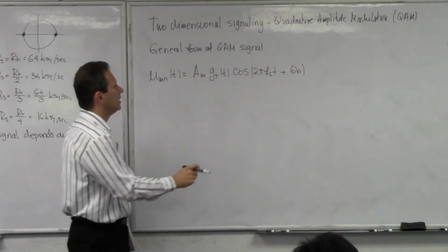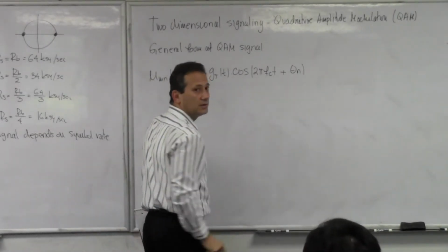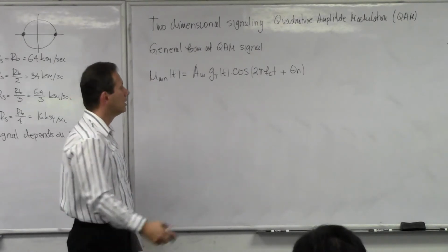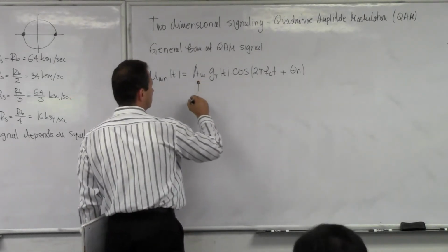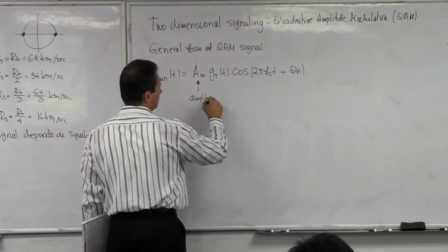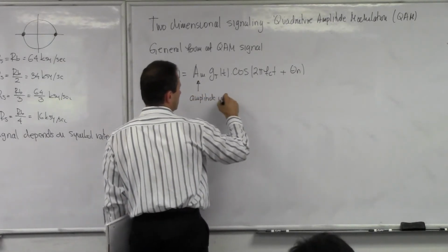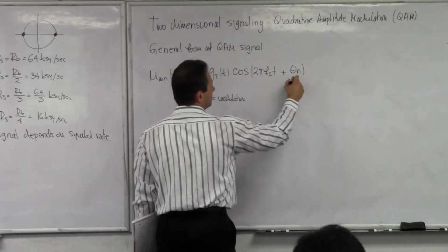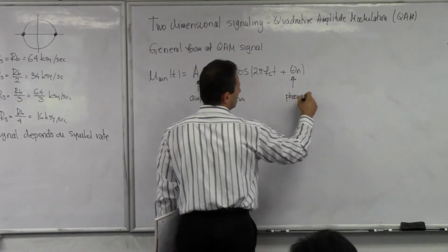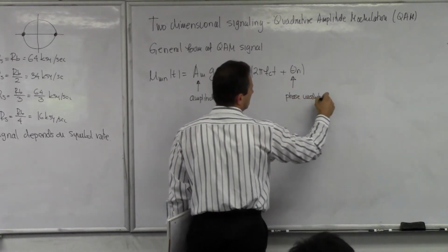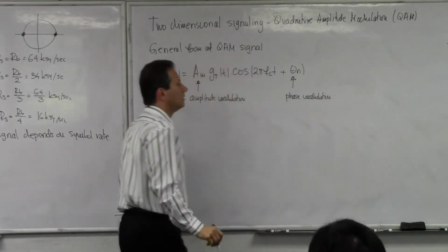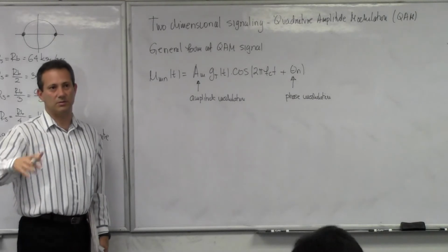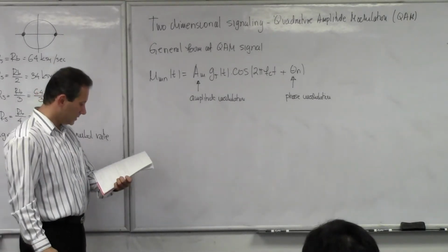In the case of the PSK, we messed only with this theta here. We had different angles, you know, as a function of whatever comes in. Here we have amplitude modulation and phase modulation working in, you know, in parallel. So we change the magnitude of the symbol as the symbols are changed, and we change their phase.